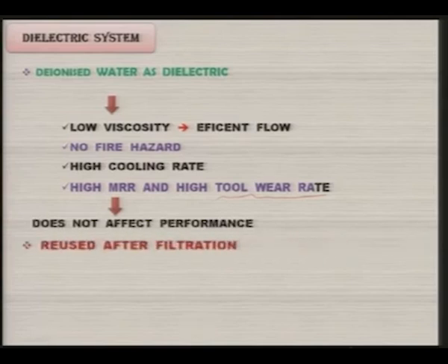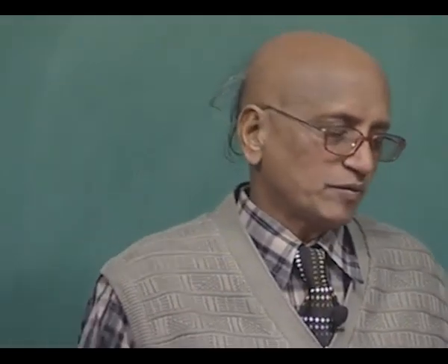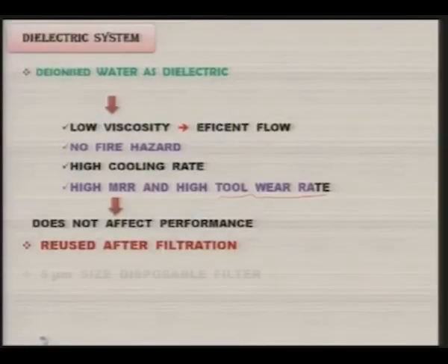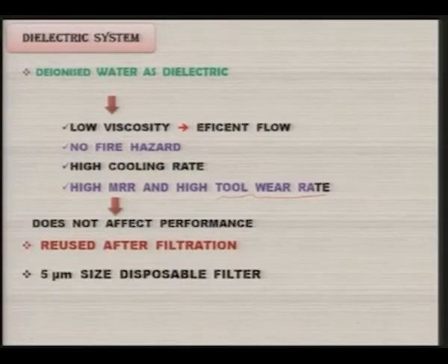The dielectric, that is the deionized water, can be reused after proper filtration. You have to use very fine filters. You can use filters of 5 micron size which are disposable. You should not keep reusing them for a very long time.